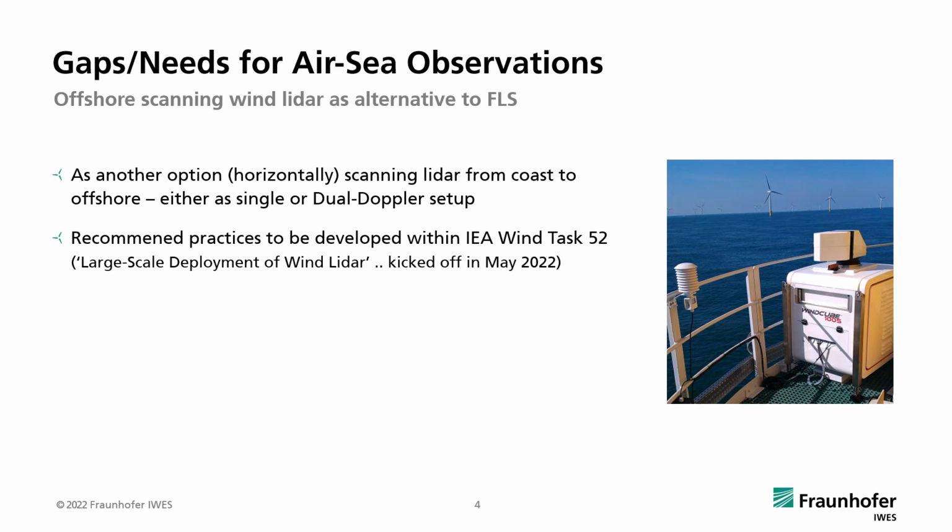Another offshore wind measuring technology is referred to as scanning wind lidar. A scanning lidar is again a lidar remote sensing device, but in this design scanning horizontally from a platform or also the coast to offshore, either as a single instrument or dual Doppler setup. These kinds of applications are particularly of interest in some parts of the world, where it is, for example, difficult to get permissions to anchor a buoy just for the wind measurements. So there are some areas where the industry looks more into floating lidar. In some other parts of the industry, it's really this technology. So there's a kind of alternative to go for the one or the other, but these two technologies can also be seen in a complementary way.